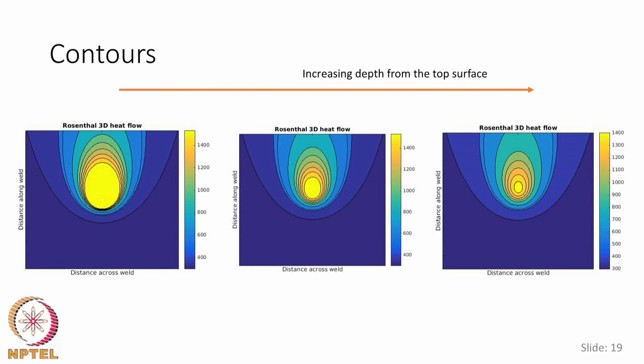So, you can use the Z variable and see how the temperature distribution is present in the entire thickness of the plate, and plot the temperature profiles in different manners. You could use contours in any of the directions that you want, x y, y z or x z, to see how the temperature contours are lined up, to see in what direction the heat is flowing, and then confirm your understanding with the thermal model that is present.